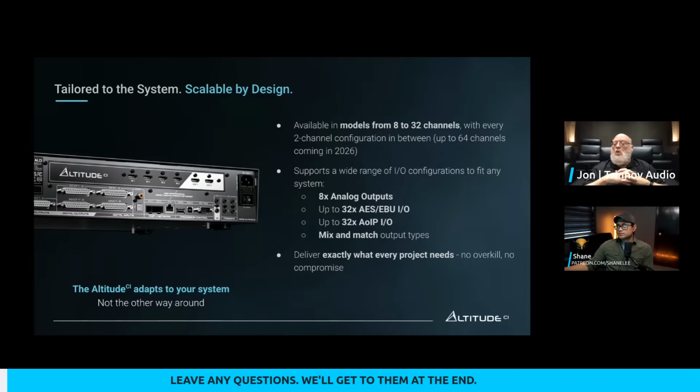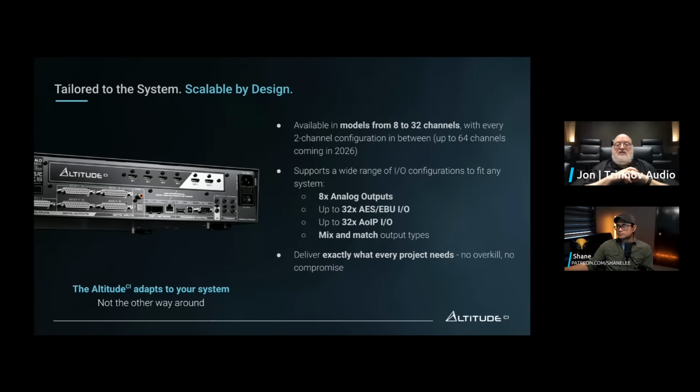There are a few requirements in order for that to work well, but you have basically a single RJ45, Cat 6 kind of cable going between the Altitude CI and one or more power amplifiers. They get converted to analog in the power amp, and everything's distributed by the network. So you can do as many channels as you want on one skinny little wire. It's pretty amazing.